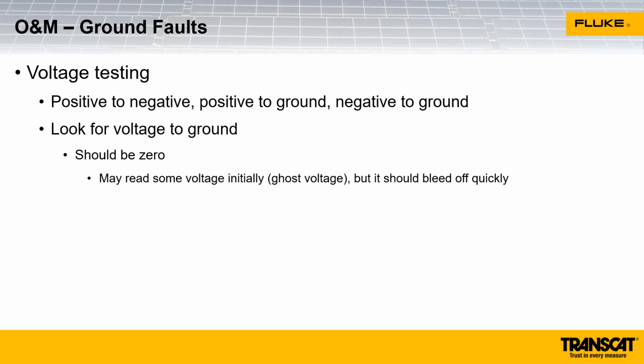On most inverters, when the array is disconnected from the inverter, if you've got a combiner box that disconnects both the positive and the negative, or if you shut down your inverter and remove the ground fault protection device fuse, or if you have a non-isolated inverter, the array is not grounded when the inverter is off. So there should be, in most cases, no reference to ground from positive or negative. So when you test from the positive or negative to ground, there should be no volts.